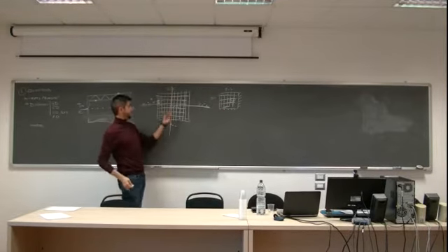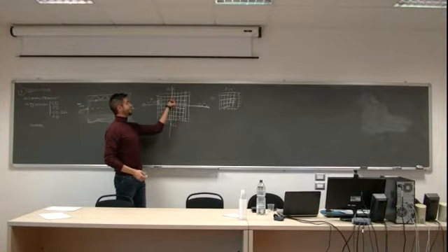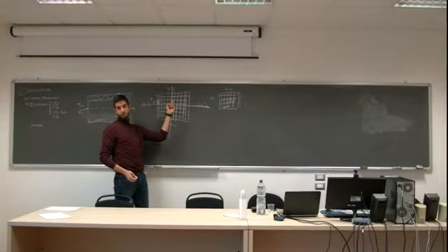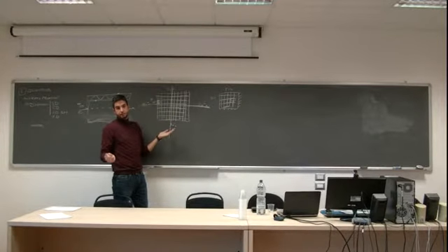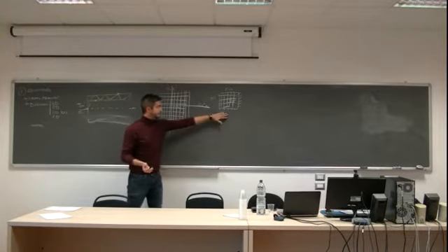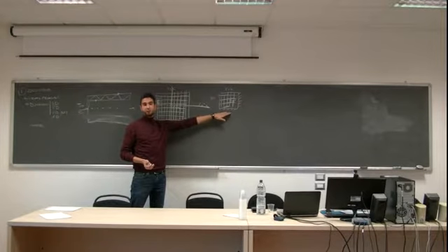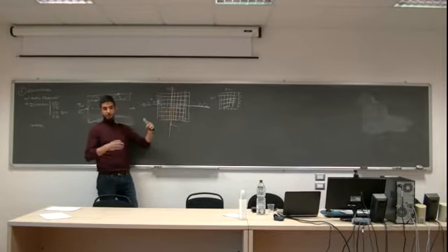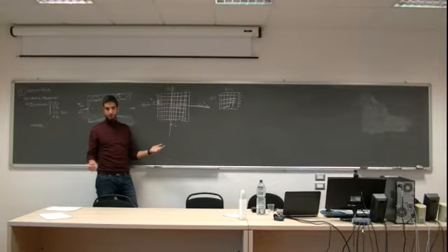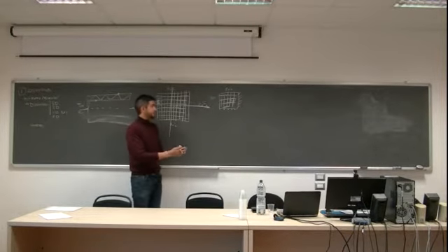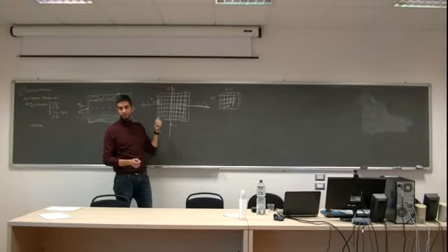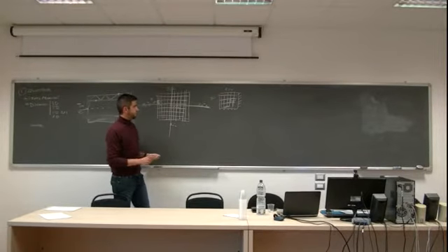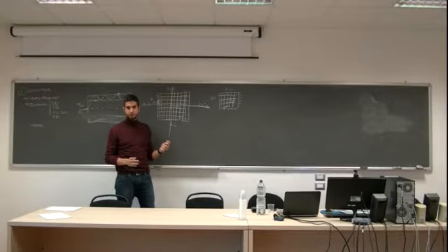Why adiabatic? Because as this node has the same temperature as this node, there will be no heat conduction between them. So this is adiabatic. This is computationally 25% of the cost of that one. And it solves the same. But try to reduce as much as you can. Symmetry is a very good tool to do it. Questions about that? No?